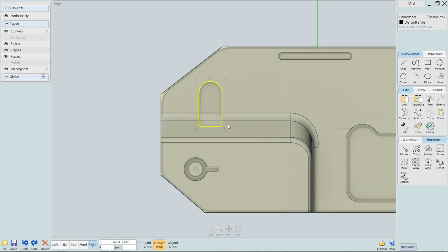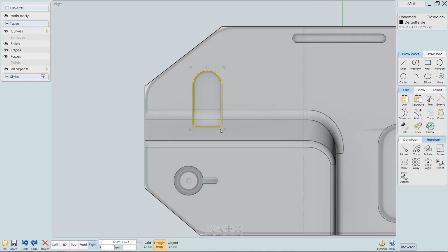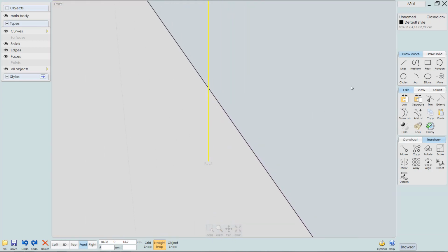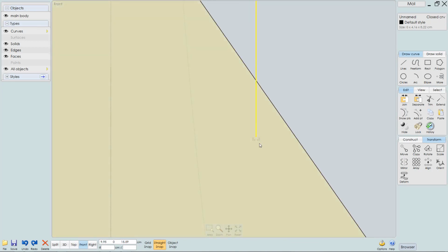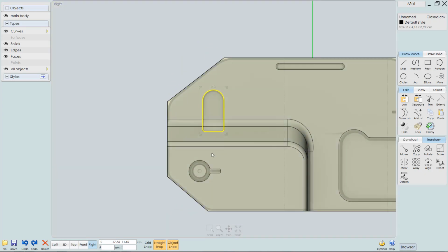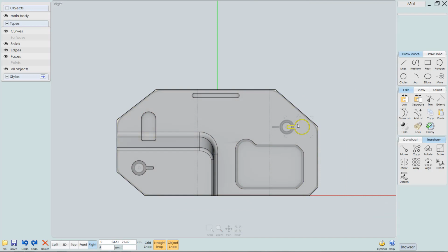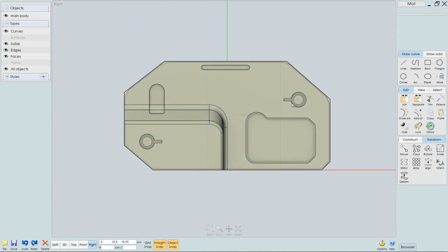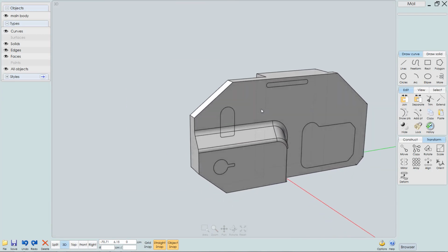Let's hit Alt Q to unhide everything again. And we probably need to adjust the position of this again. And it looks like the points were not aligned, so I just scaled them down and made them flat. And now I'm going to move this object over and snap it to the surface here. Okay, so that's looking good.